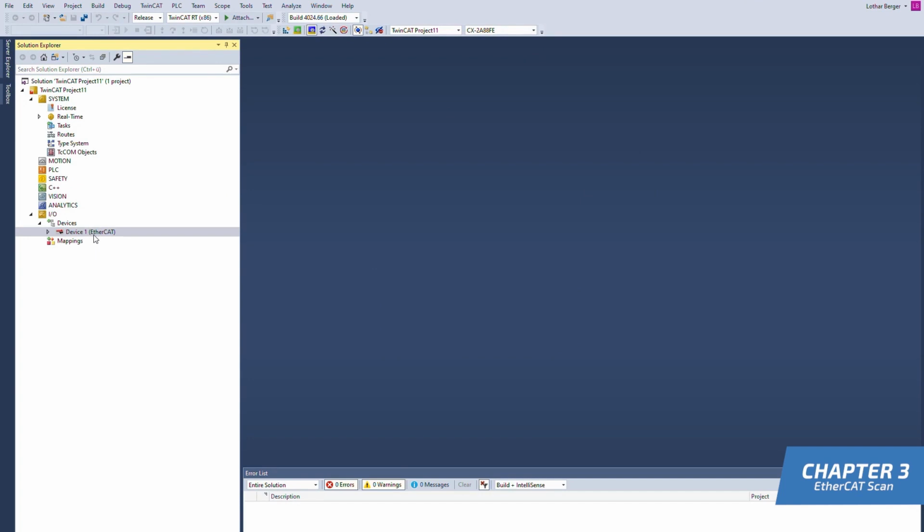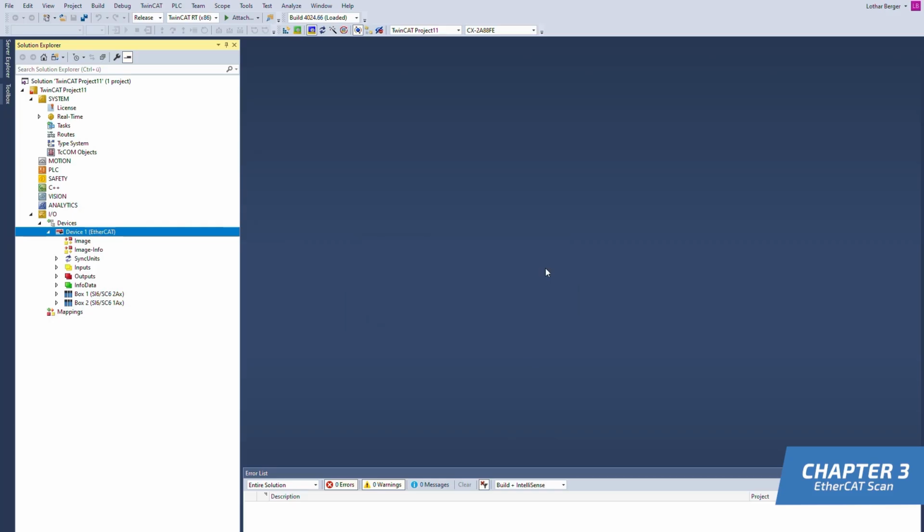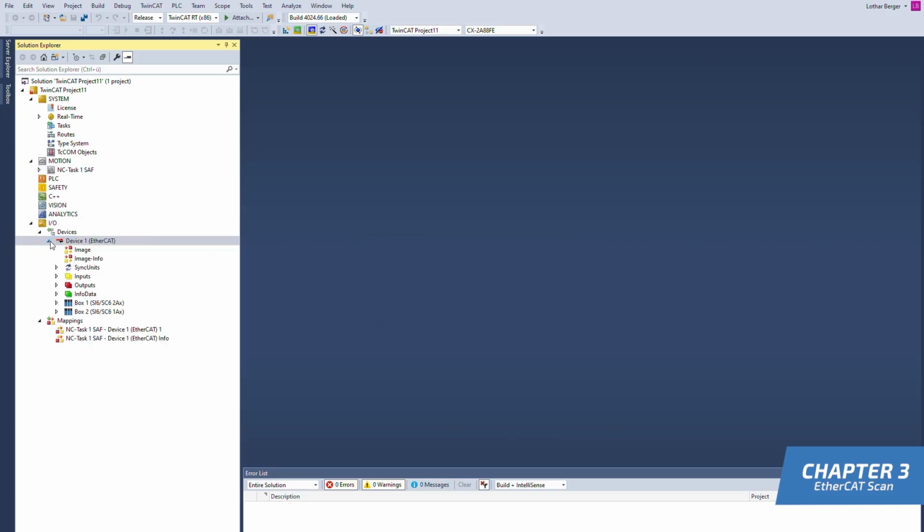If we have created an EtherCAT master and are online in configuration mode and connected to the controller, then we don't need to add the STOBER drives individually offline in the planning. Instead, we can simply right-click to perform a scan and directly add the axis to the NC configuration. In our case, it found a double axis and a single axis from STOBER drive technology.